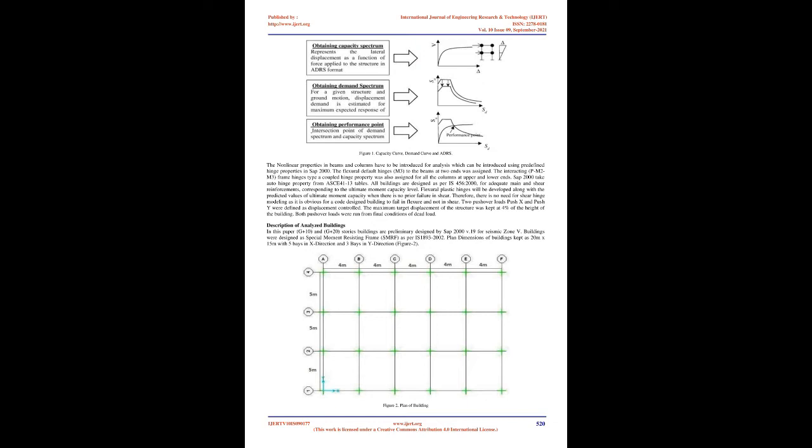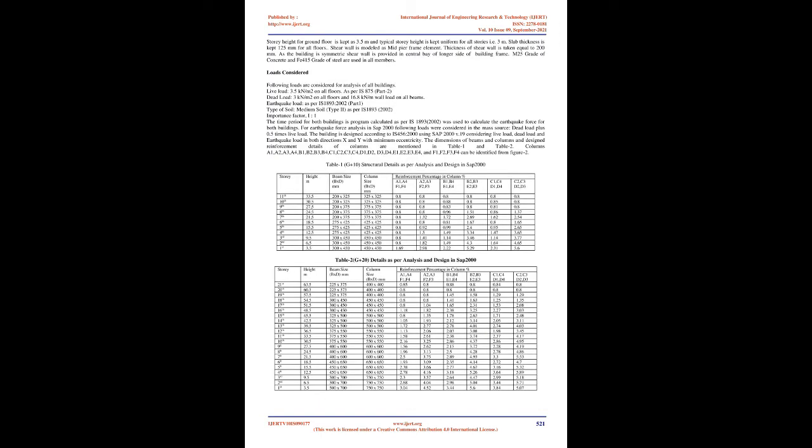The concept of performance-based seismic engineering uses nonlinear analysis to evaluate the behavior of a building. The most accurate nonlinear analysis is time history analysis, but it is very complex, requires many computations and time, and is not practical for every design. So from a practical point of view, nonlinear static analysis, also known as pushover analysis, gives acceptable results. Pushover analysis is an incremental static analysis used to determine the force-displacement relationship, or the capacity curve, for a structural element. The analysis involves applying horizontal loads to a computer model of the structure incrementally, i.e. pushing the structure, and plotting the total applied shear force and associated lateral displacement at each increment, until the structure reaches a limit state of collapse condition.